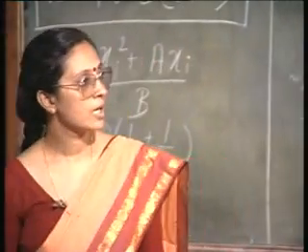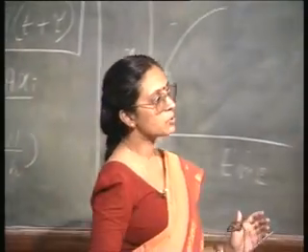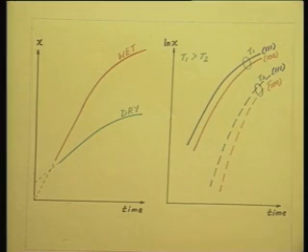Okay. So, this is one interesting point. Notice that for wet oxidation I do not have anything like this. For wet oxidation it passes straight through the origin. Only for dry oxidation I have this problem, shows a non-zero intercept of about 270 angstrom.